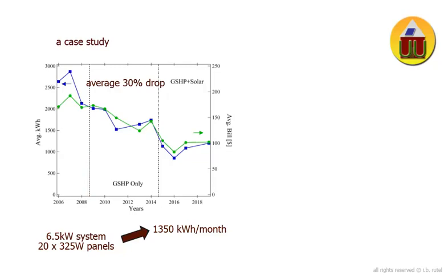While this intervention is not the focus of the story, it is worth mentioning that the sizing of the solar panel system would have been much larger to accommodate the higher energy use if it had been installed before the geothermal unit. Performing actions that minimize your energy use, like changing the HVAC or adding insulation, is always suggested prior to installing energy production systems. This way, the sizing and the cost of the generation system is minimized, and energy-saving changes tend to be less expensive than power production changes.